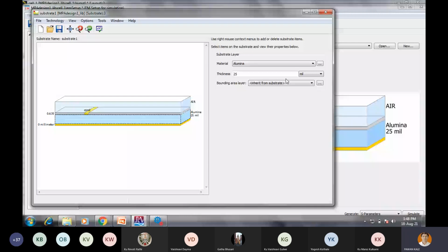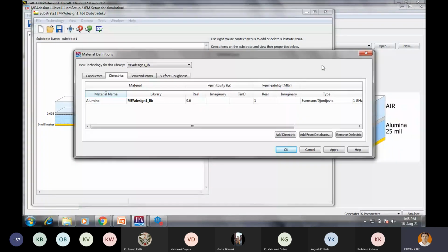तो यहाँ पे ऑलरेडी एल्यूमिना मटेरियल है, हम एक नया मटेरियल बना लेते हैं. ओके, सो ऐड डाइलेक्ट्रिक मटेरियल. ये डाइलेक्ट्रिक को लगे तो हम नाम देते हैं, लेट्स से FR4. जनरली FR4 substrates are used for the microstrip patch antenna design, flame retardant substrate. Now it is having certain permittivity. So let's say it is having the permittivity 4.3.